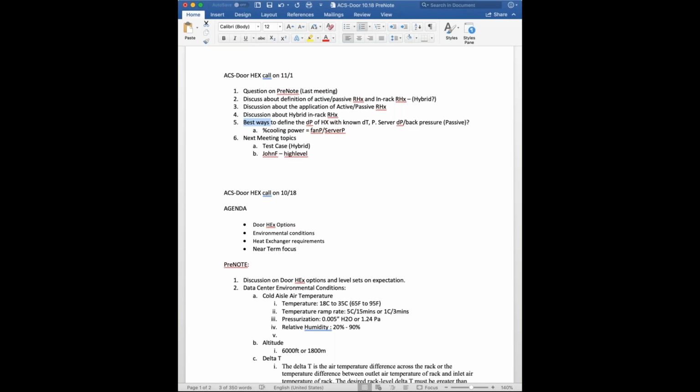So on the topic, Ronald, I guess the amount of air is also a function of the limitation of the heat exchanger performance. And what I've been reading a lot is that there is a minimum approach velocity or a linear feet per minute requirement to sustain adequate performance of a heat exchanger. Some people say 200, some people say some other number. Is that something that we need to define?